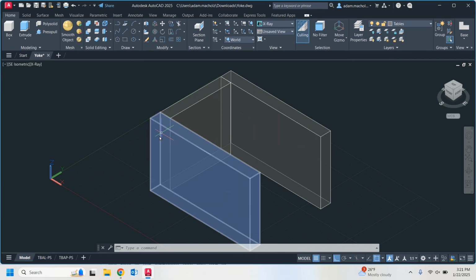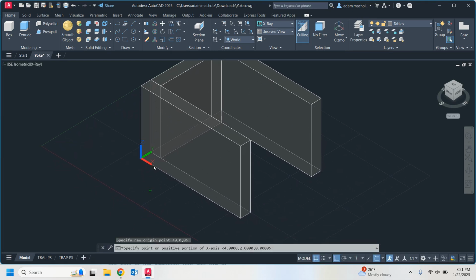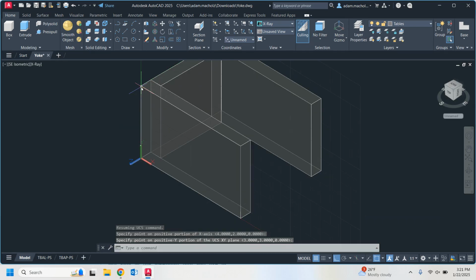And I want it to be on this surface out toward me right here. So I click this. I'm going to click my first corner. So I'm going to go to the first bottom left corner there. I need to move a little bit my view. I need to pan. Click that endpoint there, and then I'm going to come up and I'm going to click this endpoint there. So when you select 3 things, you can define a plane.